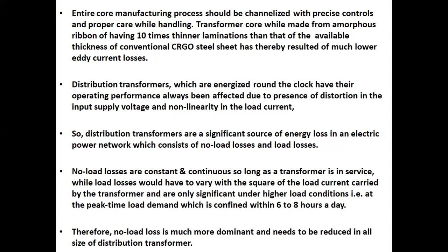No load losses are constant and continuous, so long as a transformer is in service, while load losses would have to vary with the square of the load current carried by the transformer and are only significant under higher load conditions, that is, at the peak time load demand, which is confined within 6 to 8 hours a day.